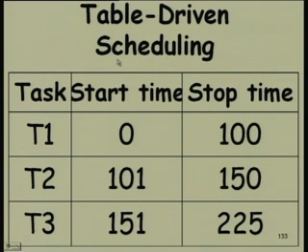Typically, what the scheduler will do is start task T1, set a timer, and as the timer interrupt comes, it will take up the next one, even if the task is not completed. Yes, that is the difficulty with this. If for some reason it cannot complete by then, it will just be stopped and the next one started, that is all.